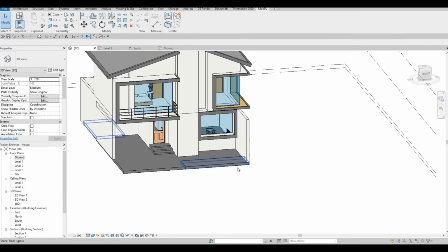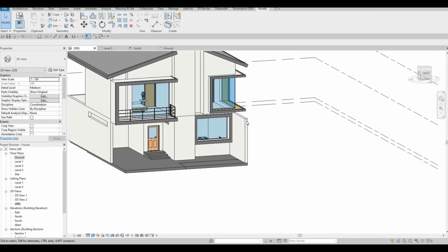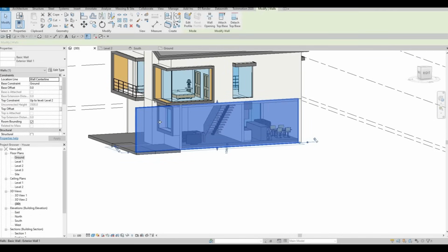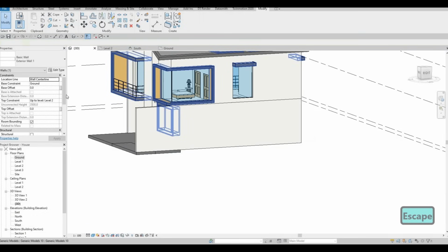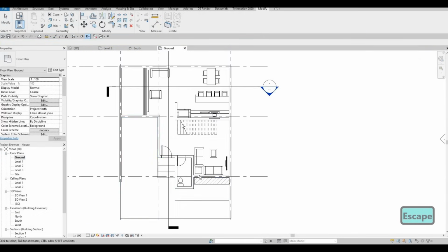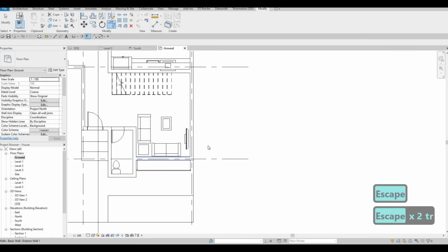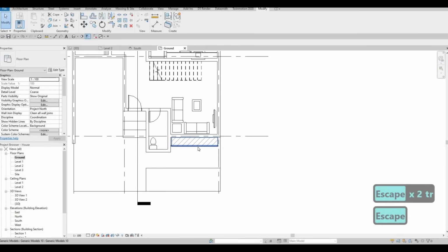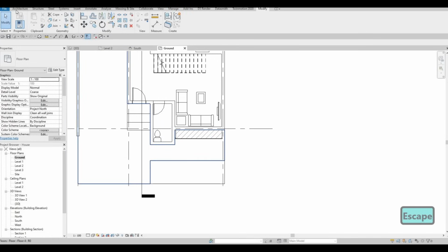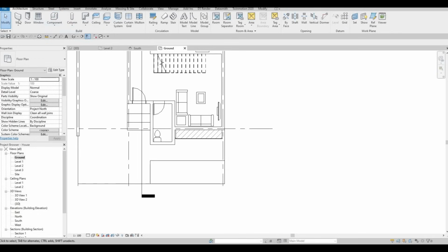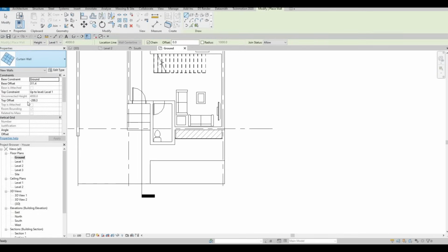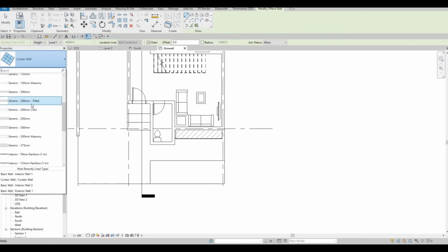And then we're going to add in our sidewalk and a border wall. So this one, actually what I'm gonna do here is go to ground and then push this back again, trim and extend. And then I'm going to create a ground for us. So I'm going to create a wall, exterior wall.